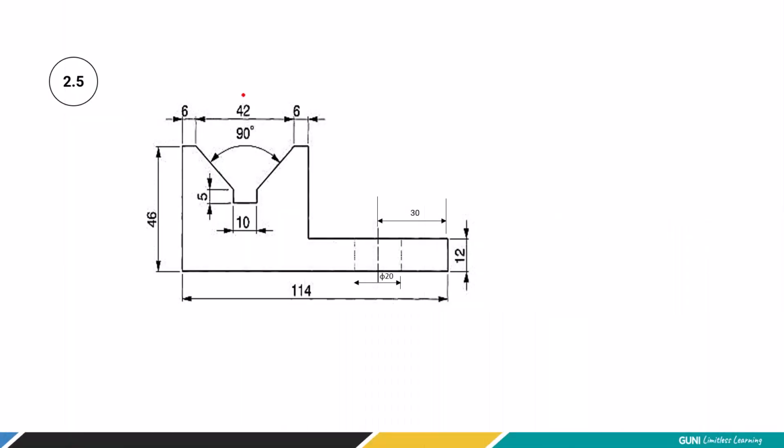Student, in this exercise 2.5, let's discuss how to complete this. First we are going to draw this horizontal line by given dimensions. We are going to draw vertical line of 46 millimeter, then by 6 millimeter. Then we are going to draw this line 12. After that we'll start again line command and we'll leave the dimension by 42 millimeter. Then again start from this point in a right direction by 6 millimeter. Then we'll move downward and we'll drag this line to meet over here.